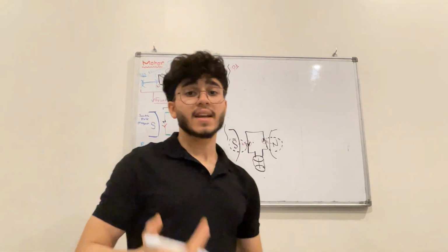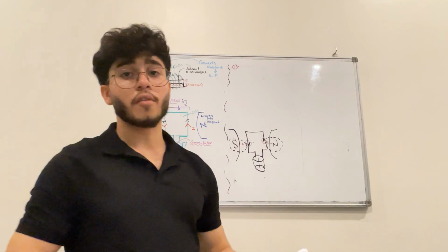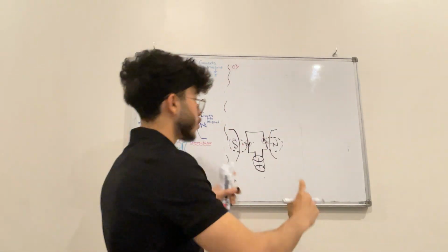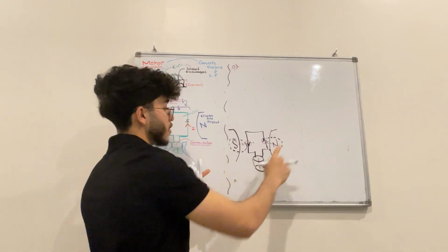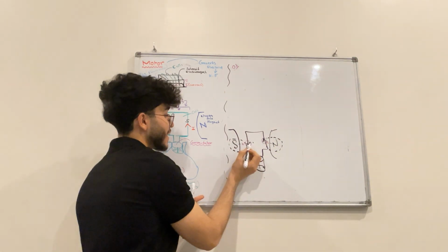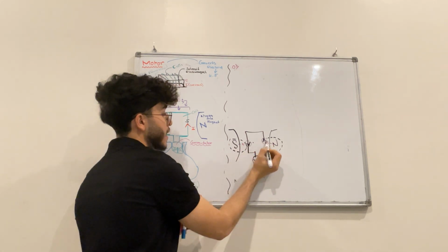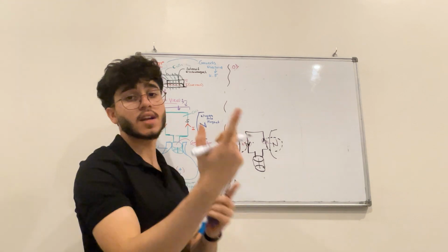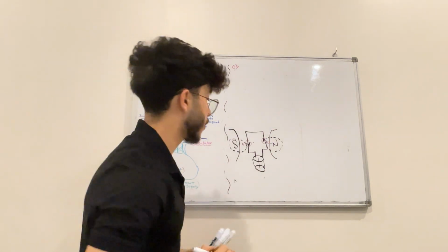Because we said current induces magnetism, so if you reverse the current, the magnetism will also reverse. So instead of you switching these magnets, just reverse the current, so every half spin, the magnetism or magnetic pole on the coil is going to reverse itself, so it will allow for a 360 spin, okay?